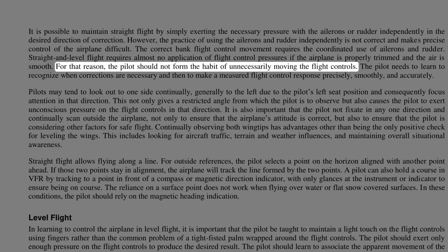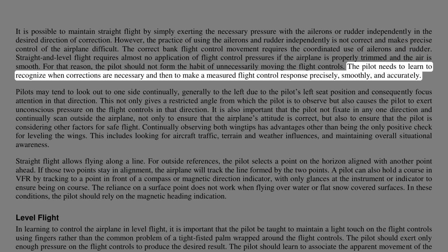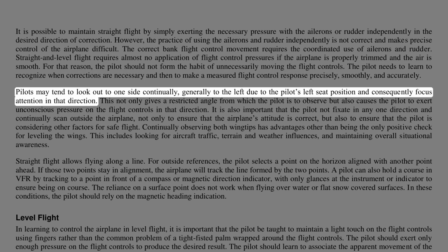For that reason, the pilot should not form the habit of unnecessarily moving the flight controls. The pilot needs to learn to recognize when corrections are necessary and then to make a measured flight control response precisely, smoothly, and accurately. Pilots may tend to look out to one side continually, generally to the left due to the pilot's left seat position, and consequently focus attention in that direction.